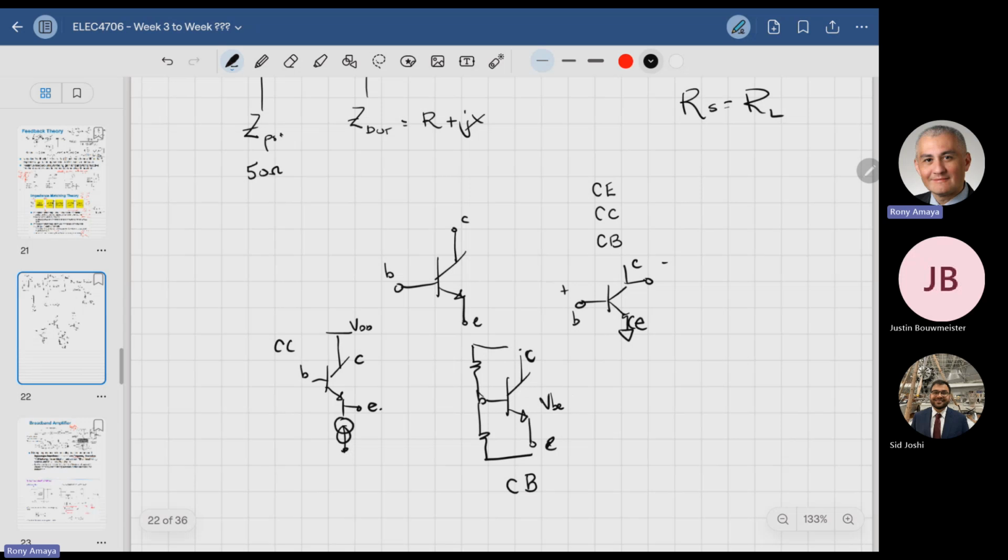Remember, I say DC or AC. We were lucky enough that in the common collector, I could DC short VBE. And is VBE a short? Not DC, but what about AC? Yes. Okay, so it is an AC short. In the case of the emitter, we can just put it down to ground and it's a DC and AC short both. And in the case of this one, we cannot really satisfy it in DC, but I can come back and add a very large capacitor, and I'm going to call it C large.